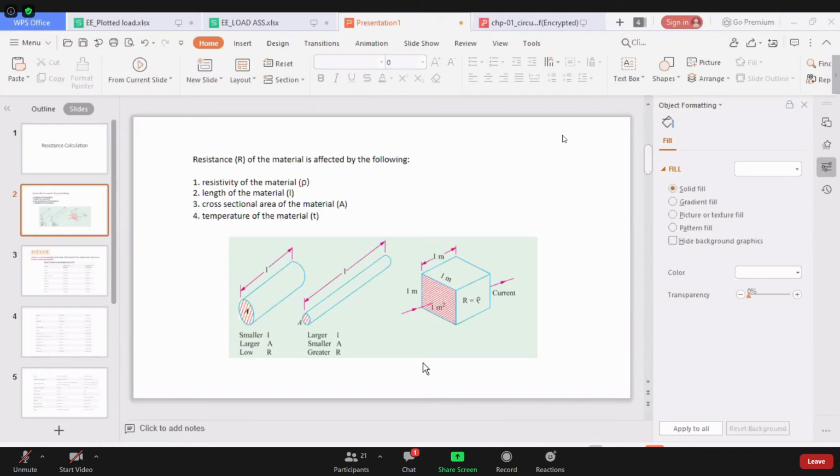It is like an allowance, no? So it is the same with our transformer. That extra 20 volts is actually the extension or the extra volts, so that when you reach your load end, if there is a voltage drop, it is still within the standard voltage or the allowable voltage. Okay?